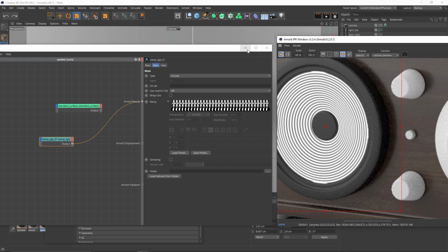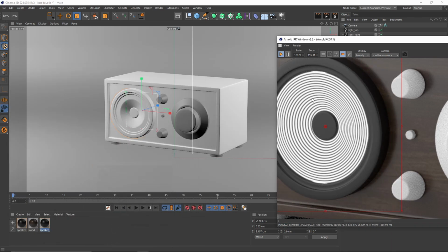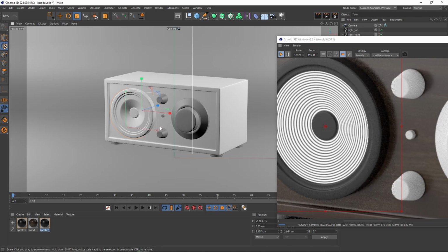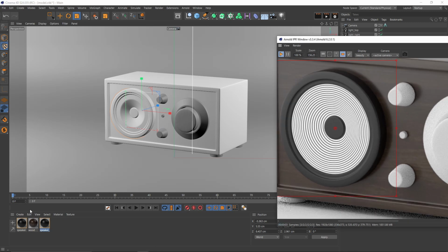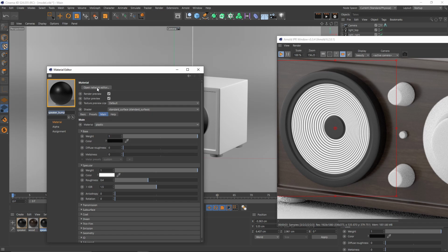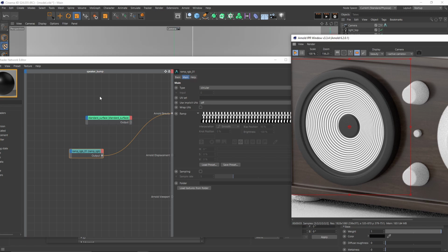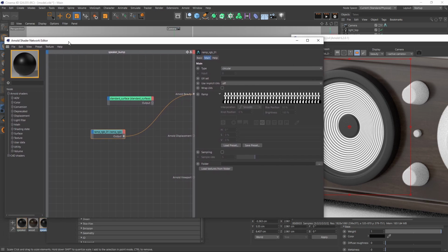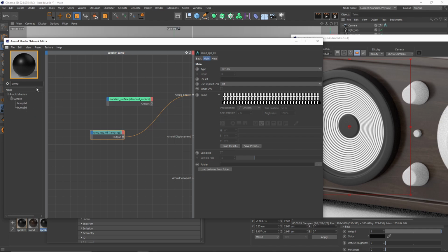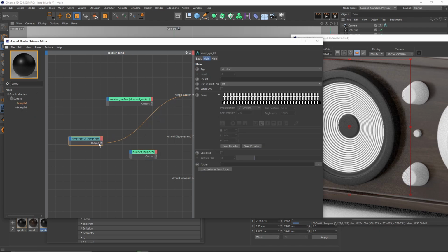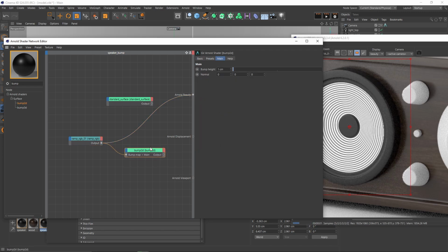I think that's good, but it looks like I need to scale it. You can see the edges. Yes, that looks good. But I want that gradient map to only affect my normal or bump. It's really easy to do that. Just look for bump, select bump 2D, link that ramp to your bump map, then select your bump node and connect it to your materials, geometry, and normal.